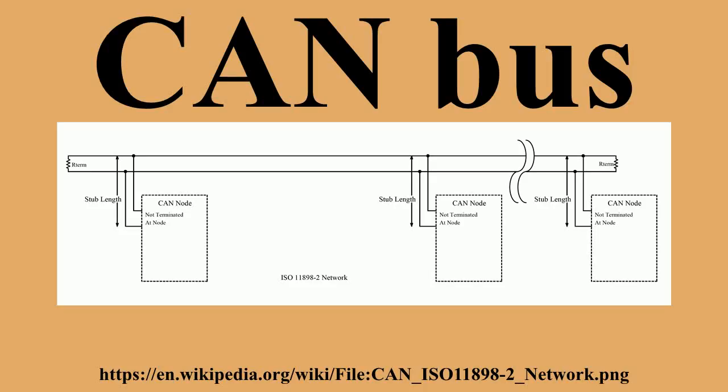Best practice determines that CAN bus balanced pair signals be carried in twisted pair wires in a shielded cable to minimize RF emission and reduce interference susceptibility in the already noisy RF environment of an automobile. ISO 11898-2 provides some immunity to common mode voltage between transmitter and receiver by having a 0 volts rail running along the bus to maintain a high degree of voltage association between the nodes.